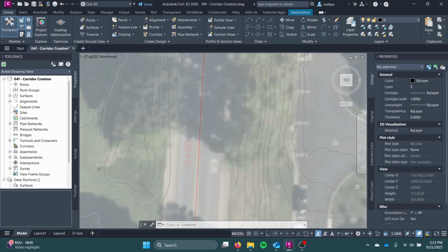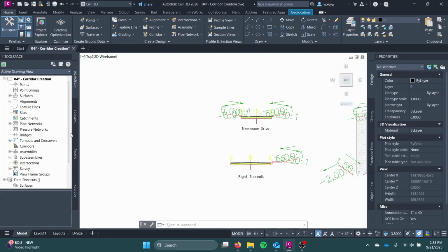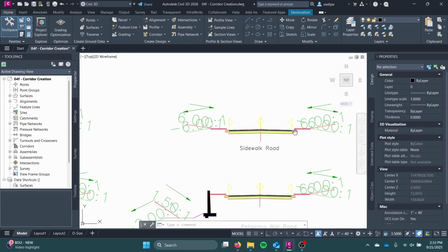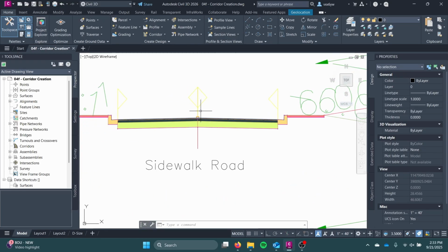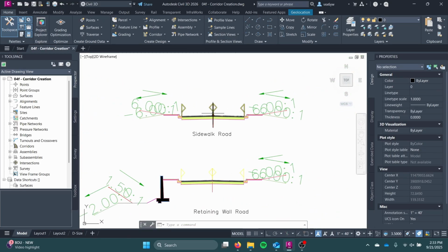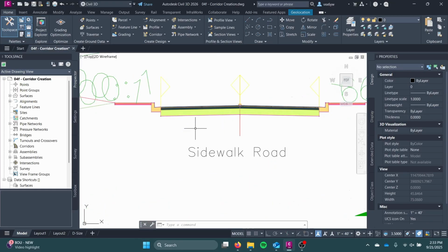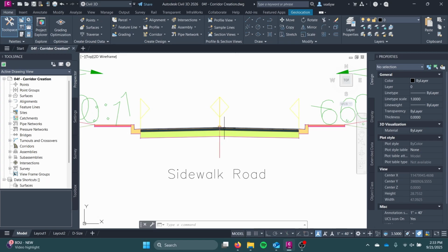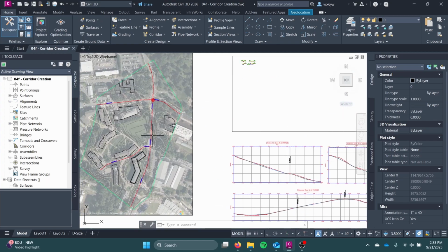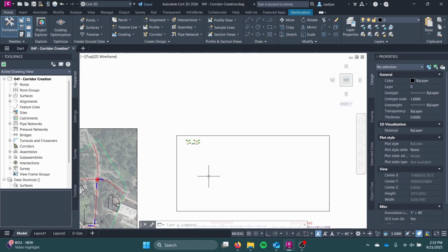And what that basically means is it takes the center line of your section, for example, right here, and it creates the geometry of the section at that specific point in the alignment. So given the horizontal and vertical data, and that's determined by the alignment and the profile that we made.